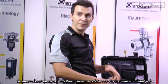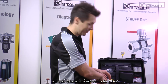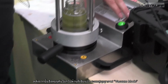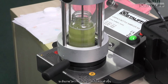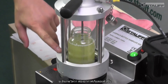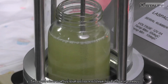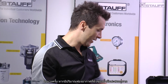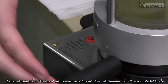First step is to remove all the air out of the sample. So make sure you close the valve. Turn the handle to vacuum. Turn the bottle sampler on. You can see a lot of bubbles up here. Make sure all the bubbles have disappeared before you commence with the test. If you have too much foam, maybe you have to vent the chamber once, make sure the foam escapes, and start again.